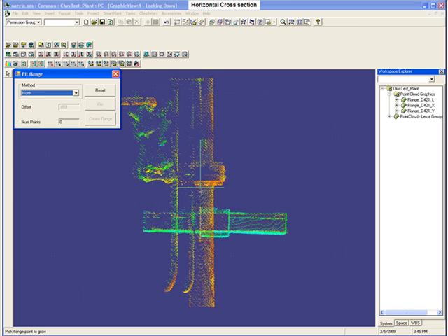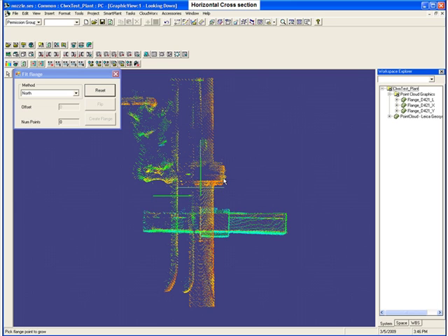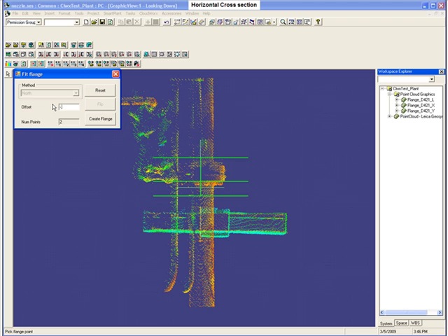Now you can see here that it was the negative distance. It depends which way your direction is going. So I'm going to reset, and I can delete these afterwards, but let me just reset again and have the tool recreate the flange. Then I'll pick the back of the flange here, and I'm going to put negative 0.059. Then you say create flange. Now you can see that I've got the flange point right where I want it, right in the center there.